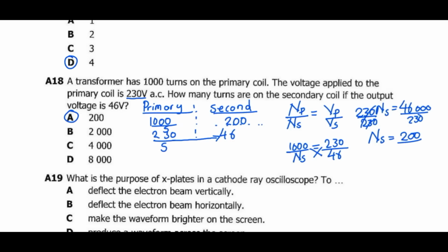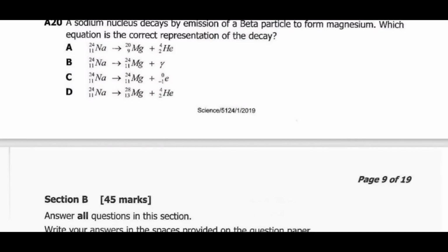So whatever method you may use, as long as you know the proportionality that works under transformers. Whatever number was used for the number of turns will be the same even with voltage. Then with current, it's just the reverse of the two. So if they were dividing by 5, current will be multiplied by that number. So that's a good pattern under transformers.